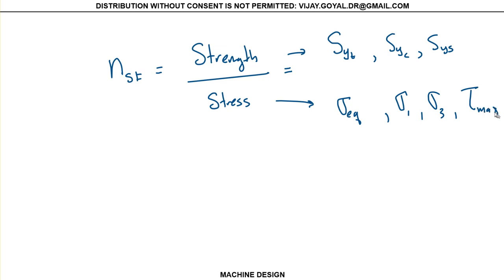The only reason we took a structure and learned how to find sigma 1, sigma 2, sigma 3 is because they are very useful when we are doing failure analysis. As an example, if compression is critical, then I know that sigma 3 would be less than 0.